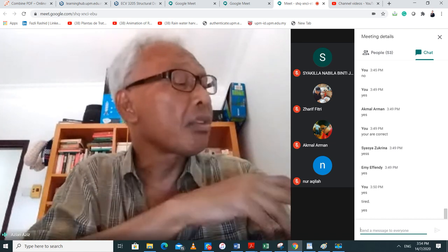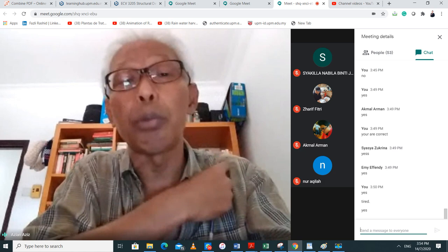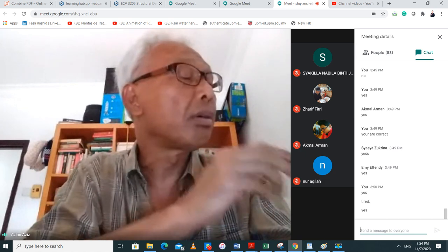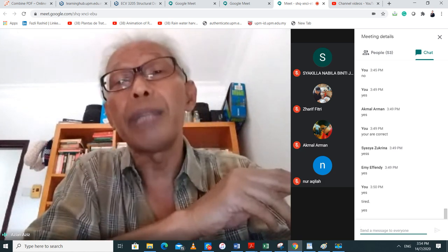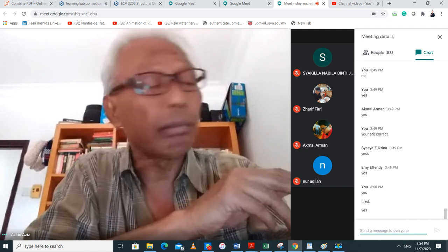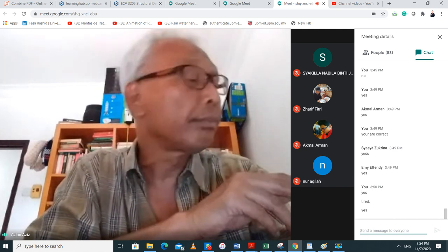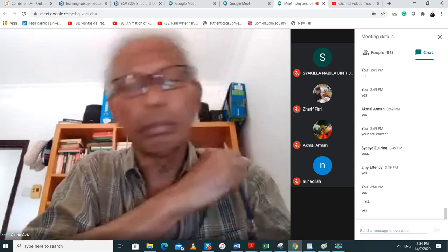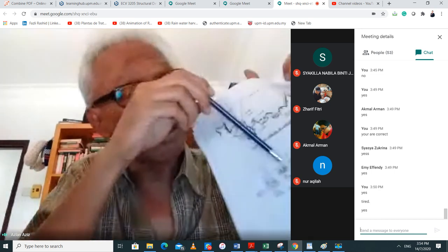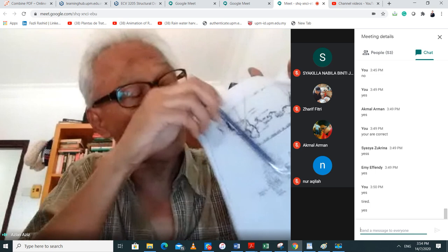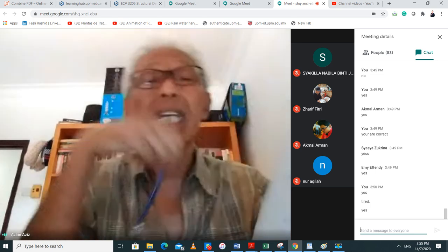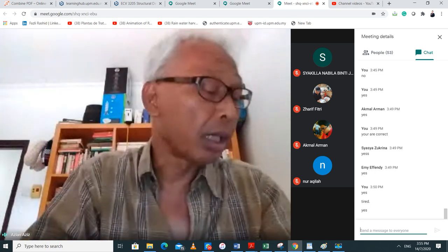And then this oxidized limestone is just a big boulder in the soil. So again, you believe that it is solid rock, but it is not. It's just a boulder in the soil. And then if you pile and it hits the sides of that rock, it's going to be bent, and then your pile is no longer performing well.